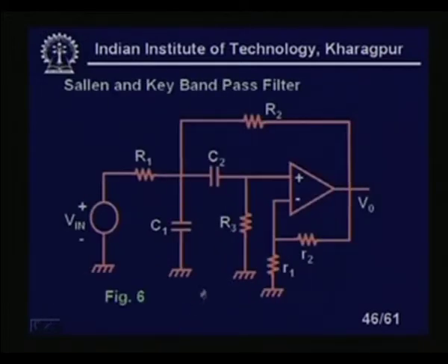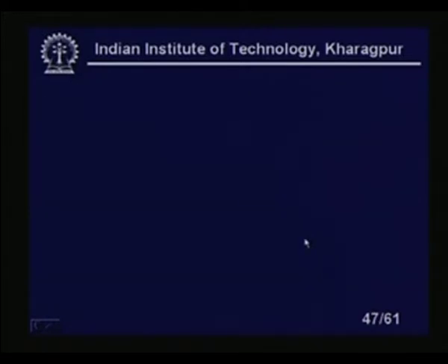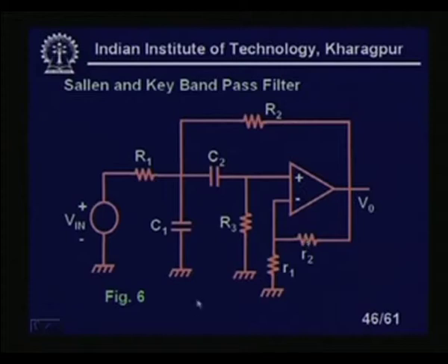So, this is the band pass filter. In the band pass case, we need one more resistor R3, all other resistors are the same as before, but the structure is slightly different, right. It has negative and positive feedback. To make the circuit stable, I have to give a certain amount of negative feedback, right. So, this is our band pass case.